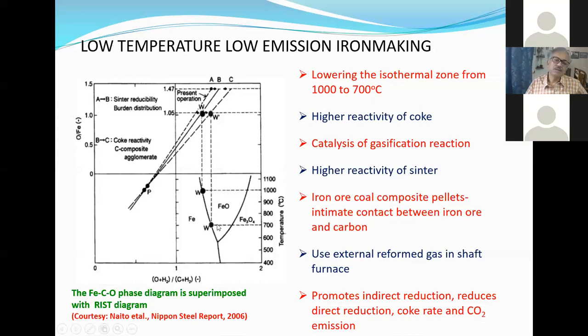This can be done by some methods. One thing is that you can increase the reactivity of coke. If you can increase the reactivity of the coke, then carbon gasification can take place even at a lower temperature. For ordinary coke, the carbon gasification temperature is around 1000 degrees centigrade. Then the CO2 plus C forming twice CO reaction becomes irreversible, that is, the CO concentration becomes very high.